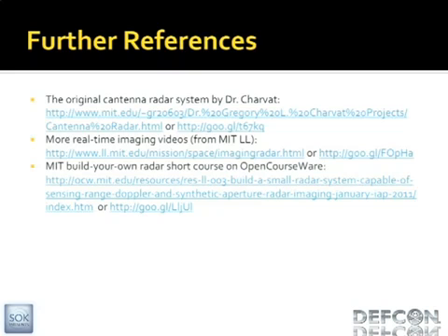Oh, well, the coffee cans are somewhat directional. He asked why coffee cans as opposed to a different type of antenna. The coffee cans are fairly directional. They were really cheap because they're coffee cans and we had them anyway. But basically, it's going to be hard to see inside this thing, so you might just have to come back later and see. The way this works is there's an SMA connector in here, and there's a little wire being fed into here. So this is basically a waveguide port. It's an adapter from that little feed antenna to this larger waveguide. And then it's basically a crappy directional antenna.